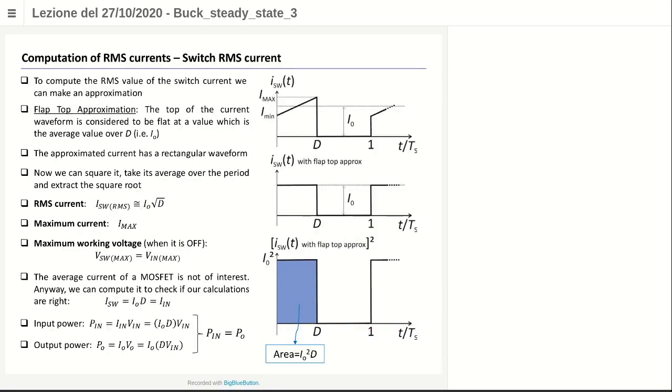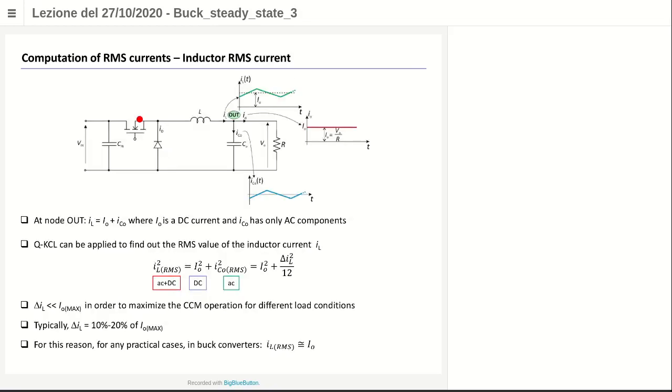Okay, another piece of information: I changed the slides for this steady state lecture because I found out that there is a graphical error in the design of the MOSFET. The N-channel MOSFET has the arrow that enters the device, like this one, while in the other set of slides the arrow points up, so it exits from the device. This is the symbol of the PMOS.